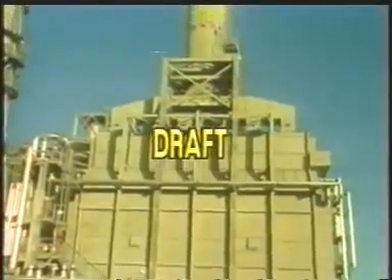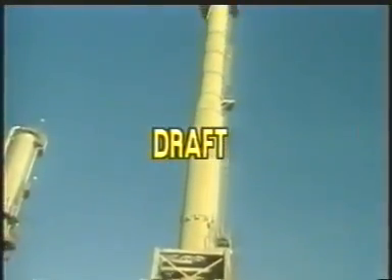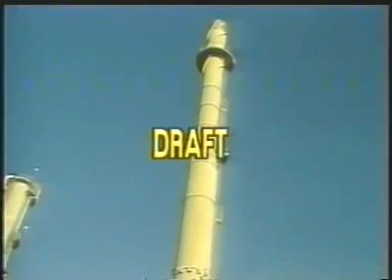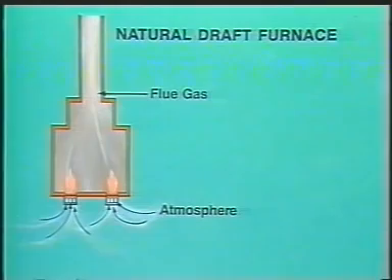The furnace draft is important because it moves hot flue gases out of the stack and draws fresh air through the registers to the burners. The type of furnace we've discussed so far is a natural draft furnace. It's given this name because the draft occurs naturally due to the fact that hot air rises. The rising flue gases cause the pressure inside the furnace to be slightly lower than the pressure of the atmosphere. This lower or negative pressure is what maintains the draft through the furnace.